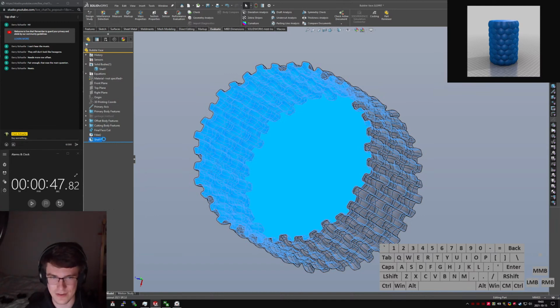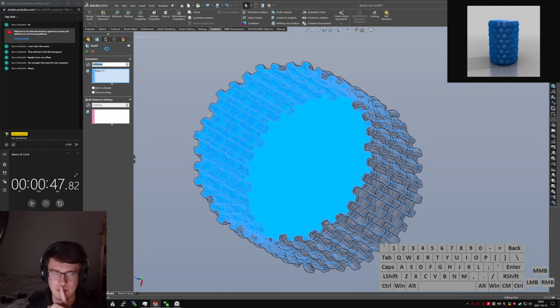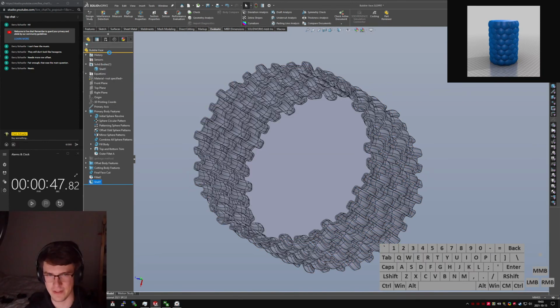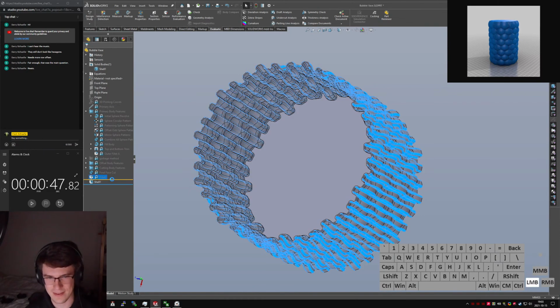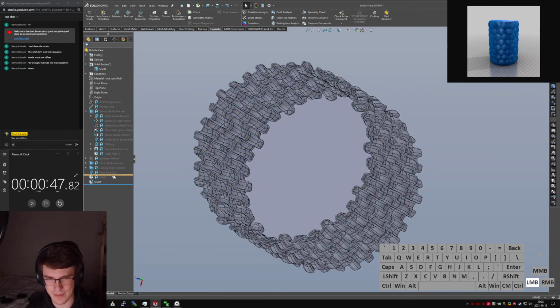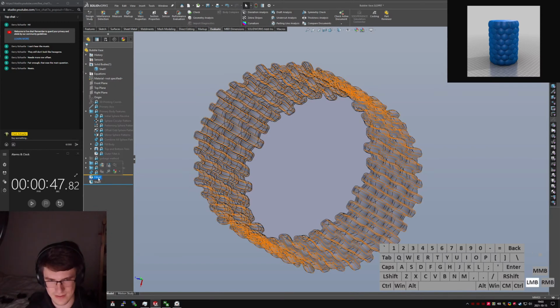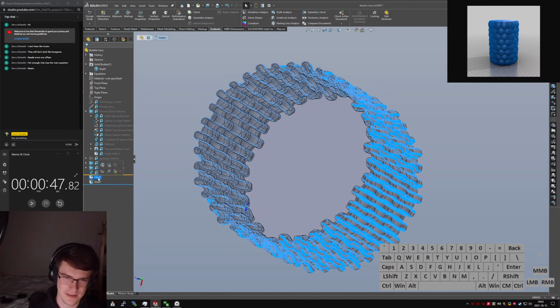Edit feature. Or no, I'm not gonna edit feature. What I'm gonna do is drag the freeze bar past the fillet so that I never ever have to rebuild that fillet. Can I rename it at least? This gets to be called the fillet of doom, I think.